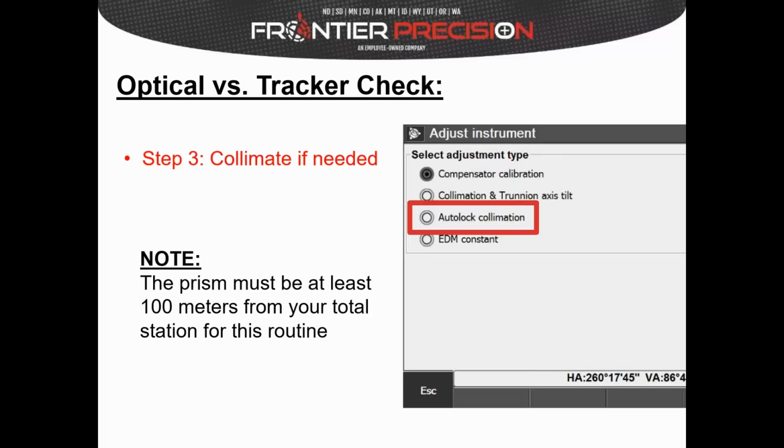The other thing to consider, within spec, is that at 100 meters with auto lock on, those crosshairs should be somewhere on that glass. If it's not on the glass, then it's not good enough. And there might also be a point where you can no longer do these collimations by hand to get them back to where they need to be. These things might get so far out of adjustment that they physically need to be opened up and some screws need to be turned.